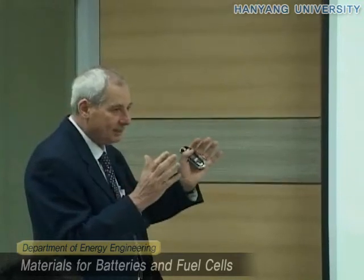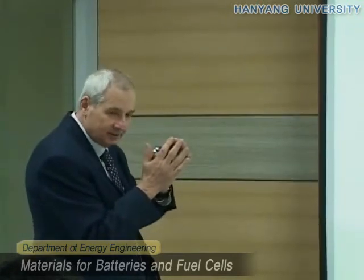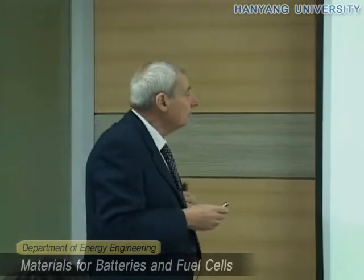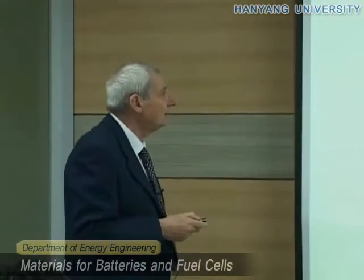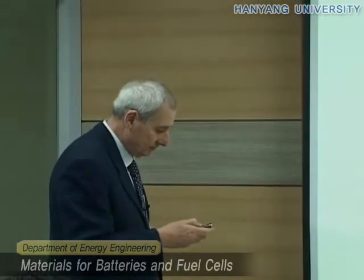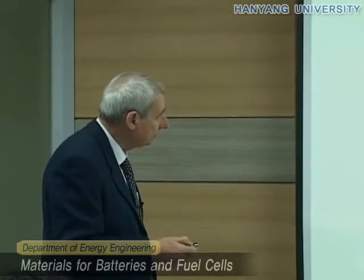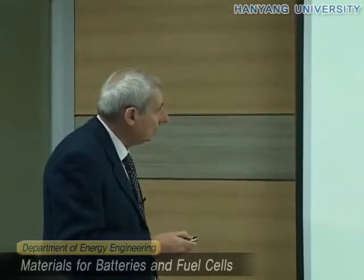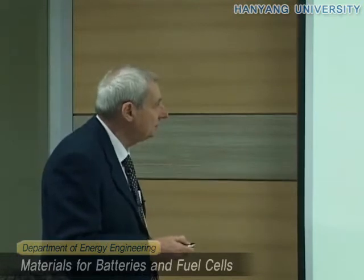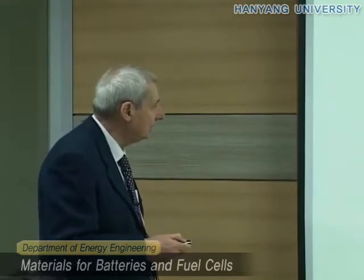The use of a separator is to bring the electrodes very close together, so as to decrease the resistance of the battery. In this case, the separator can be a porous polypropylene sheet. The conductivity is in the order of millisiemens, which is enough for making a battery operate.